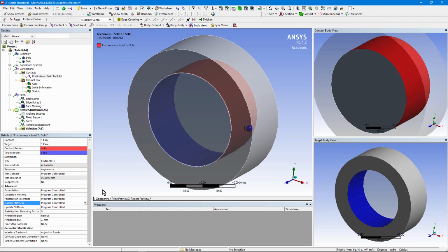That can help with nonlinear contacts. Do you update those stiffness values according to what's happening in an analysis? If I have something like a nonlinear contact between something made of rubber and steel, I might want to update my contact stiffnesses from iteration to iteration. I can put in an artificial stabilization and artificial damping to try to cope with difficult problems.